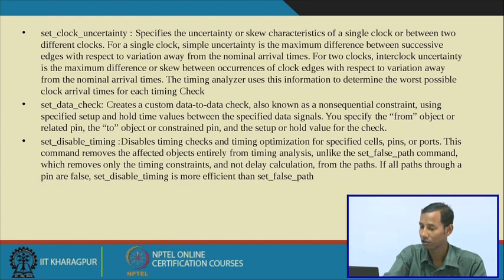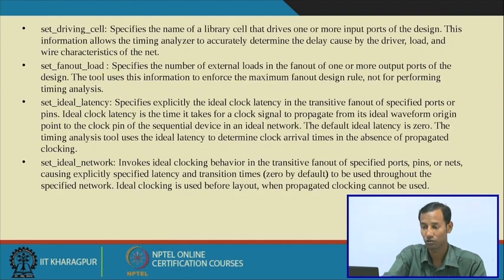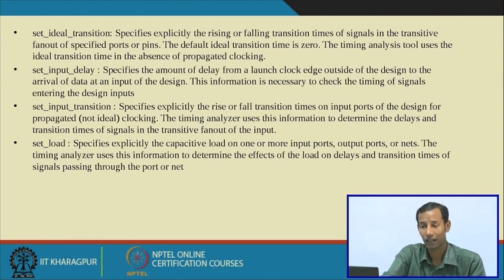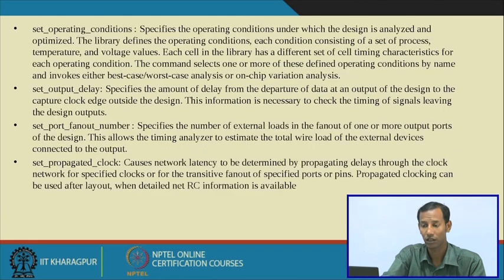Set data check also you can do, set disable timing also you can do. Then there are several other options too: set driving cell, set fan out load, set ideal latency, that means ideal value for latency, ideal network, ideal transition time, set input delay, then input transition time, set load.